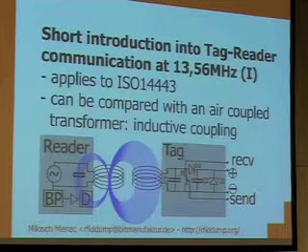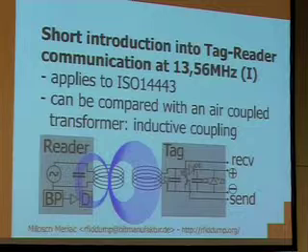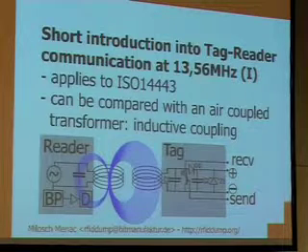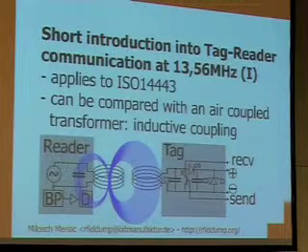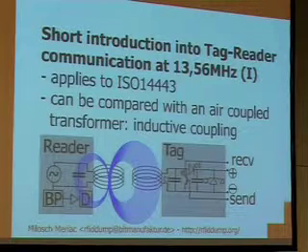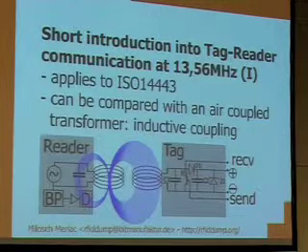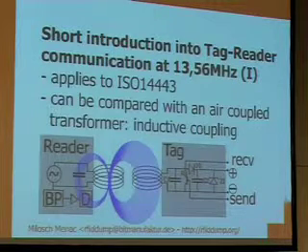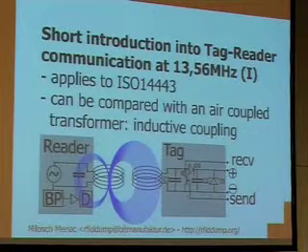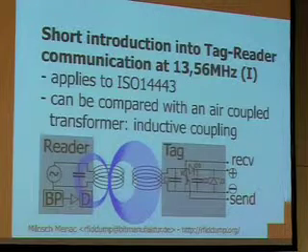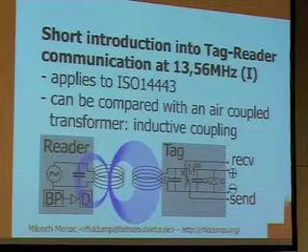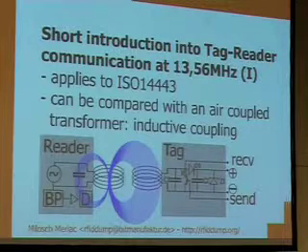So you get actually a higher load on the tag side, and on the reader side, because the reader needs more energy to keep the magnetic field up. And if the send line is triggered in this case, you get this shortage, and you see an amplitude change on the reader side. And on the reader side, you see this BP part of the schematic, and the BP makes sure that only this amplitude change is filtered out of the signal by a bandpass, and it's demodulated.